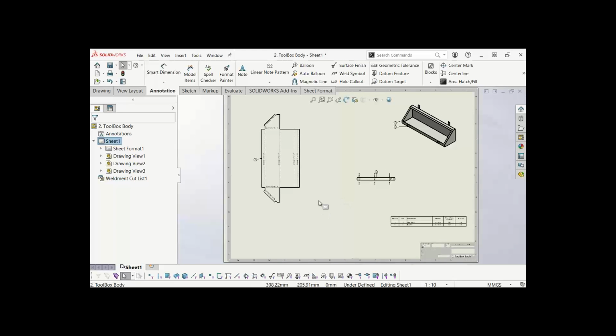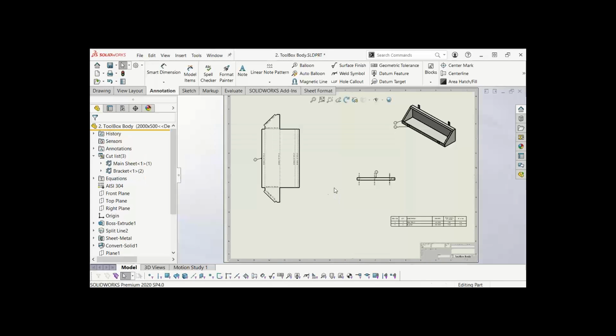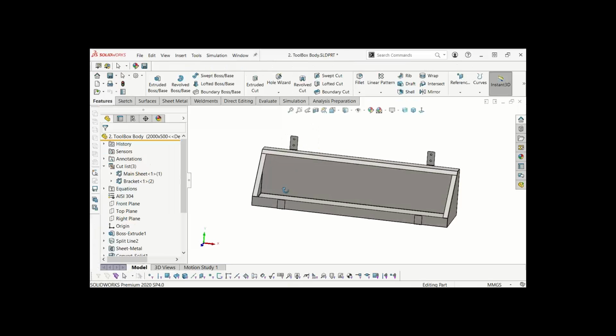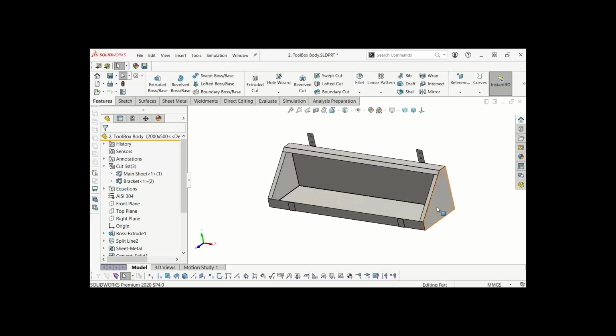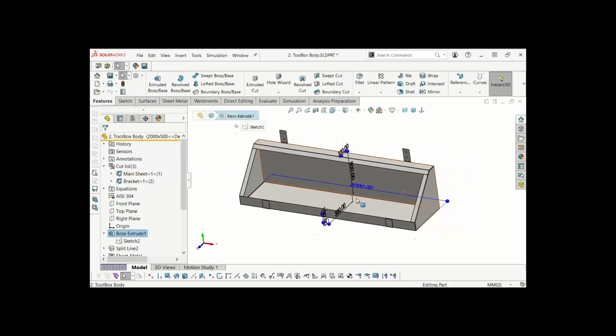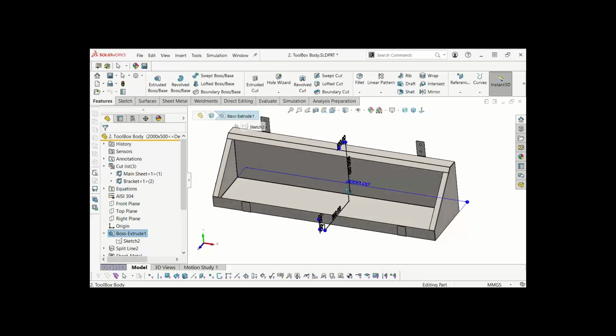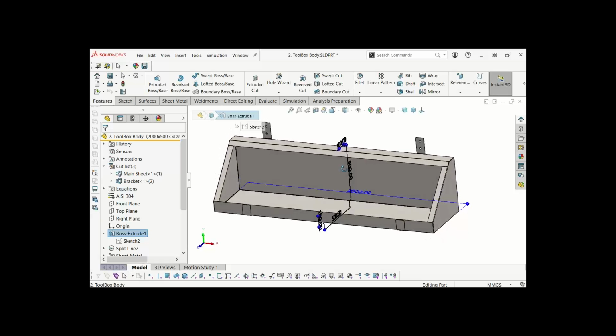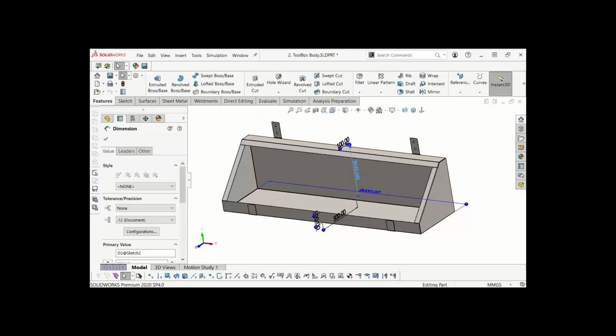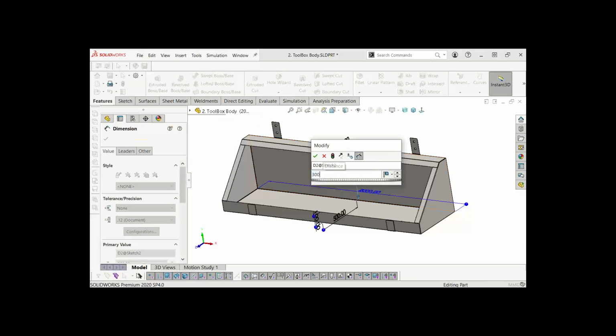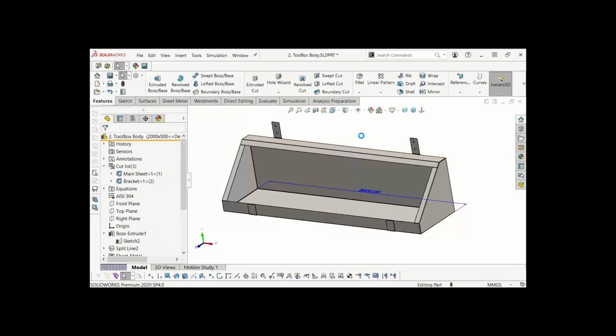Okay, so the advantage of doing this concept. What is the advantage of doing a concept like this? When I have a primitive or a base feature, it is very easy for me anytime if I want to update my dimensions, I can update them. When I update them, automatically my sheet sizes will update. So suppose, for example, I say that this is going to be 300.